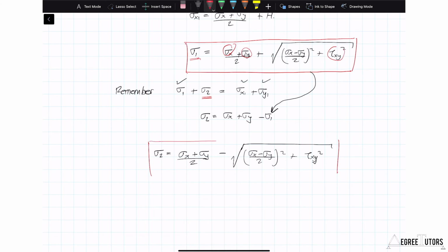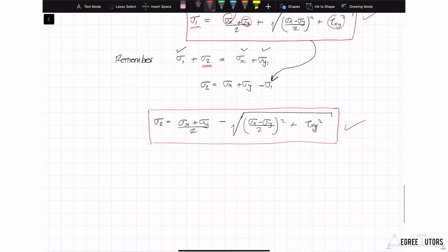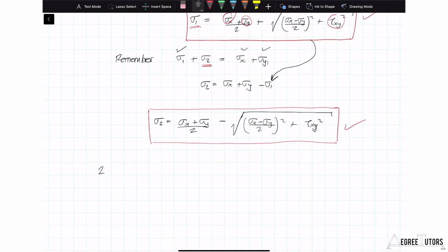So we've now worked out some key values here, right? The principal stresses are really important values to us as engineers, so that we need to know what are the maximum values of stress that develop. And now we've worked out a nice handy expression. We've got an expression for the max, and we have an expression for the min. All right then. So let's just package those up and say the two principal stresses are equal to, let's go, sigma 1, 2 is equal to sigma x plus sigma y over 2. What is that? That's just the average of sigma x and sigma y, right? Sigma average, you'll often see this written as. And then plus or minus our h, right? Whatever the hypotenuse of that right angle triangle was.